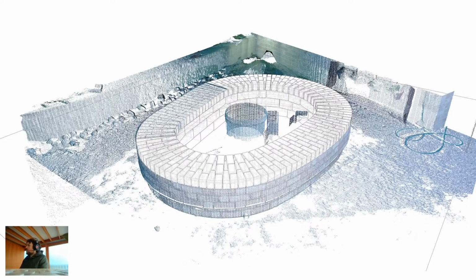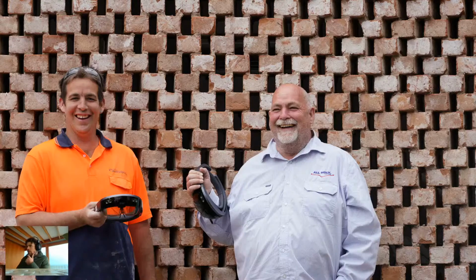This image shows the scan overlaid over the digital model. You can see on the far side of the prototype where the scan's clearly not in the right spot. And it's really interesting to see this because that little chunk of the prototype was done without the HoloLens. The HoloLens ran out of battery and they just finished off the top course, and it's by far the most inaccurate part of the structure. The rest of the structure deviates between, I think it's about 5 to 10 millimeters over the course of this thing. So that's within construction tolerances for brickwork by far, whilst also bringing about all of those kind of time savings by being able to construct it in parallel. So this means happy bricklayers within the construction industry.